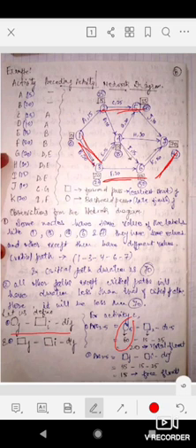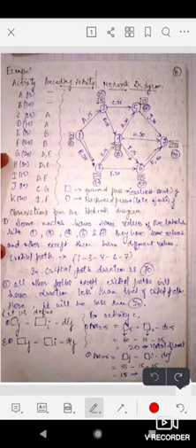For node 2, minus d25, which is 25, so we will minus 25. So 60 minus 15 minus 25 will give us 20. This is the total float. Total float means it is the extra time available so that you can delay that activity. I will tell you once again. See what is happening here.